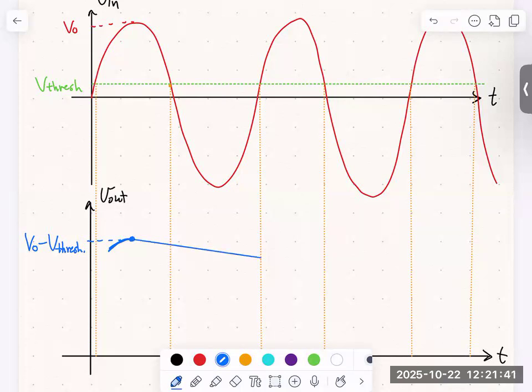And then the diode goes forward biased again because now we're back in the positive cycle of the input. And this will cause the capacitor to charge back up. So whatever charge bled off initially will be replenished. And then the discharge starts again. And then we're back to another positive part of the cycle where this climbs back up and then the discharge starts again.